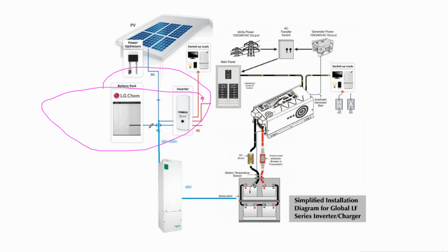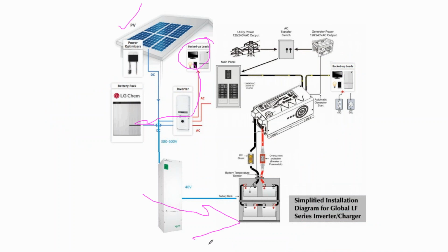And so there's actually room for lithium-ion and lead acid to exist feeding the same system, using a small lithium-ion battery bank for demand management, and then lead acid for base load. And then why would that make sense? Well, you still get the lithium-ion battery backing up the critical load. And so now I have a solar array charging my battery inverter, but also able to charge my critical loads so that if my battery inverter fails, I still have some backup power capability.